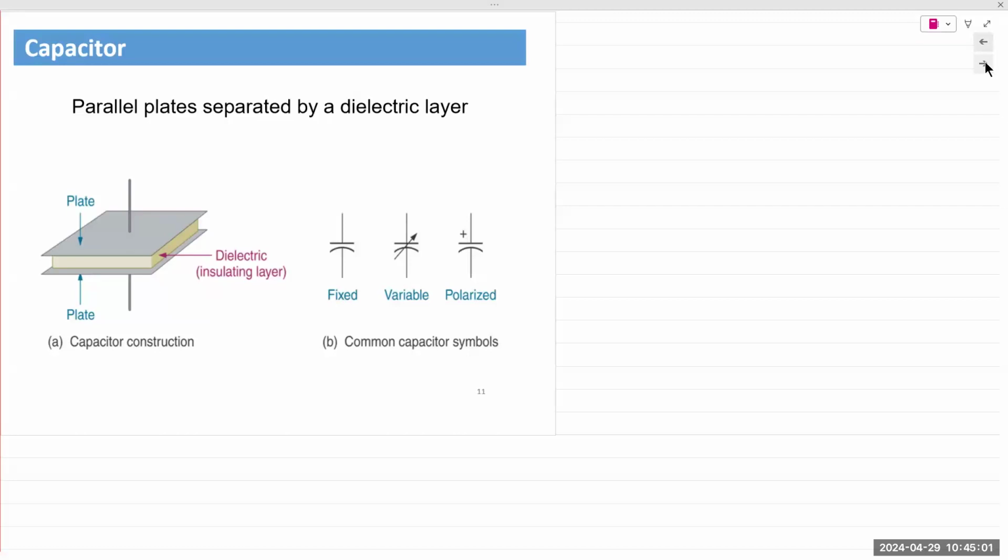Especially if it is a conducting material like a cable. A USB cable, for example, has 4 conductors flowing through it. 0 and plus 5 volts, and then 2 cables for data plus and data minus. So there's at least 4 flowing through a standard USB cable. These 4 cables are conductors that are insulated from each other, separated by an insulating material. So there is capacitance all along the length of any cable.